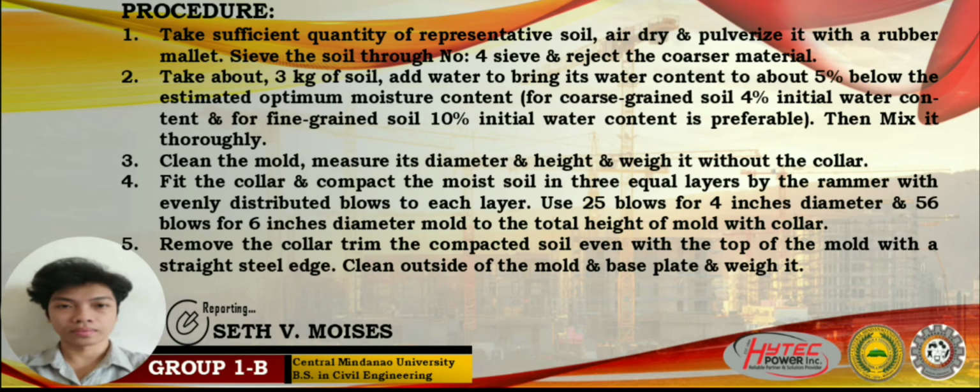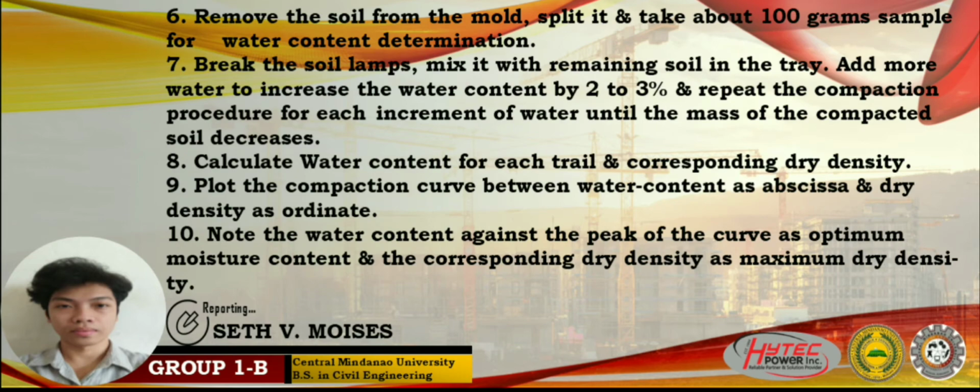Overall, the standard Proctor test or Proctor compaction test establishes the variation of the unit weight of soil and degree of compaction with the moisture content. It also helps us find out the optimum moisture content for the highest practical density.